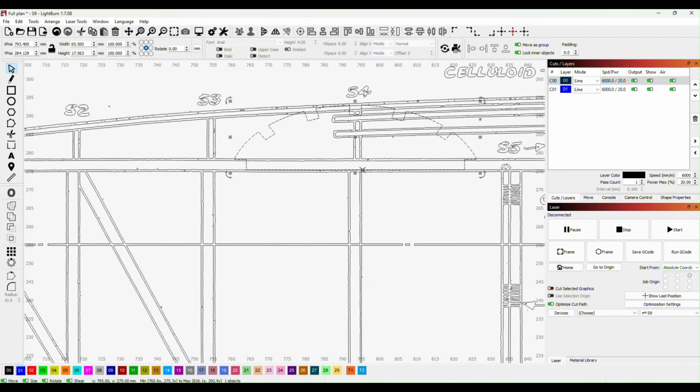So what I'll do with that is shift the whole thing up a little, and then we can go to nodes, and I can select these 2 bottom nodes just by highlighting them both like that, and then if I Control and Shift, I can bring them down until they're at the bottom of the line there. Okay, so that's dealt with those.